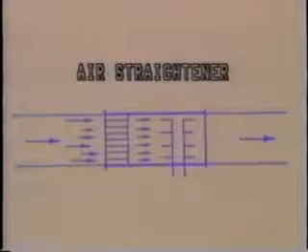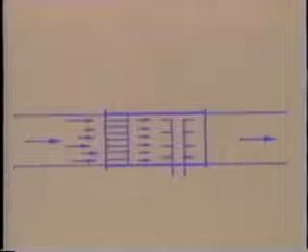Multiple point self-averaging pitot tube stations were introduced to the commercial control industry for use in controlling and indicating air volumes. When installed in the ductwork at distances from the cause of air turbulence, as specified by the manufacturer, accurate sensing of total and static pressures is achieved. The unit manufacturers claim that the air straightening devices eliminate air turbulence and rotational airflow by directing the air into a near laminar flow. The distance from a major air turbulence will determine the type of sensing station to be applied.